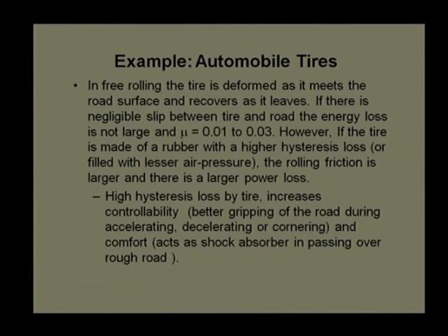When we discuss rolling friction, we are adding one more thing. When we take the example of a tire, we need to see whether the tire is completely filled with air or not. When we drive a car, many times due to lesser filling of the tire, deformation of the tire will be excessive, and that will cause a high coefficient of friction. We will be losing petrol consumption, or we say the kilometers traveled per unit liter will be lesser than with a tire completely filled with air.